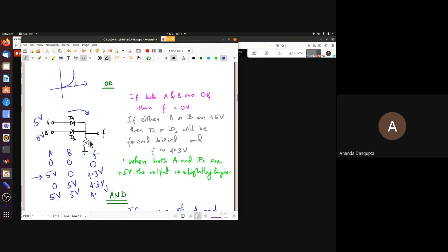So if the drop across R were exactly the same as before, then of course the current would have been halved. But even if it's not halved, it's close to halved. The smaller current actually means smaller drop, right? Okay, I admit that smaller is smaller by a very small amount. It's not a resistance, so smaller current does not mean smaller drop in that proportion. But a slightly smaller drop, which means this voltage could typically be something like 4.4 or 4.5 volts.